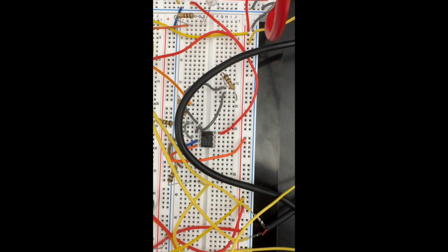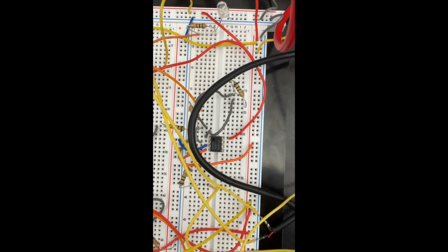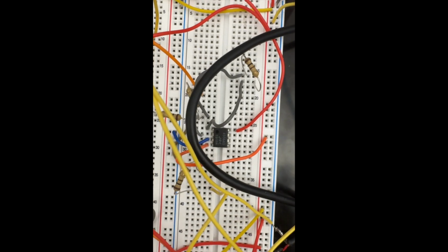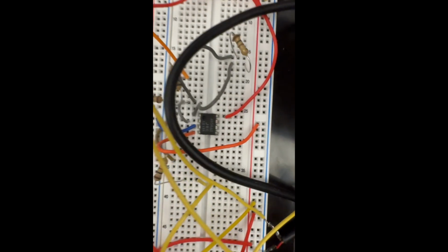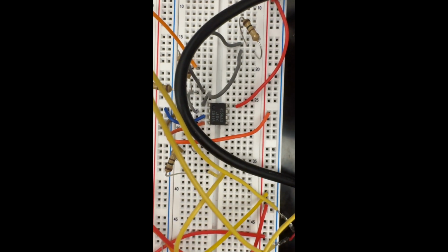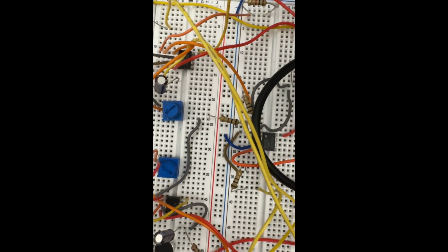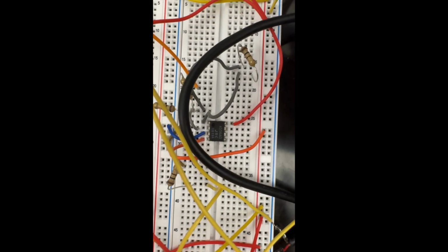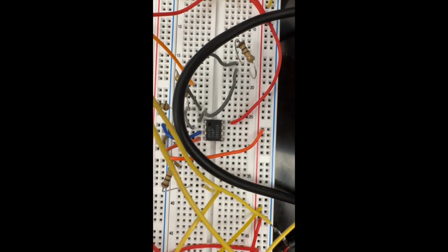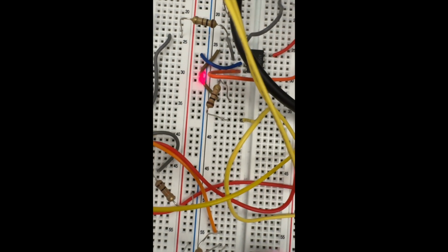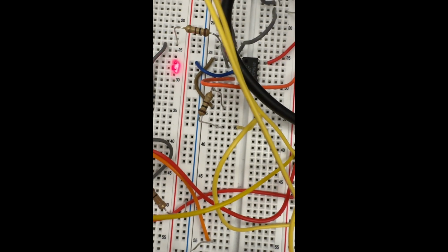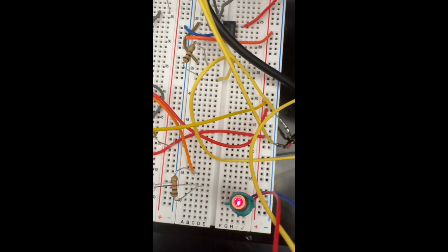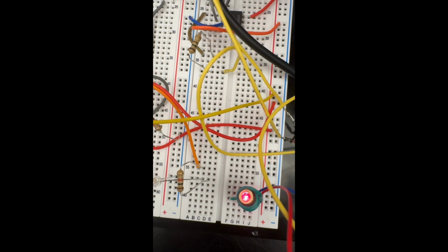And then this is my summing amplifier. It's connecting to 200 ohm resistors from the mic and aux output, and it is summing them up using the potentiometer. And then the output of that is going through this 100 ohm resistor and getting sent to my laser that is not grounded but is connected to negative 4.5 power.